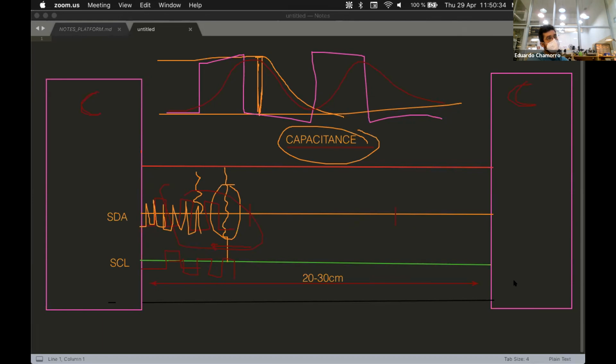So I2C and SPI both need these considerations. Take care of the length of the cables and how many jumps you have. In a communication protocol that is normally high speed, you need good connections, and you need to take care of soldering to avoid reflections, and also to have a lower capacitance on the line so that you can have a clean signal.